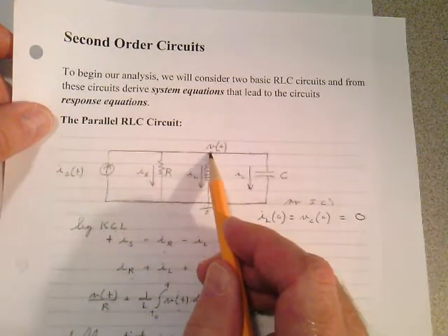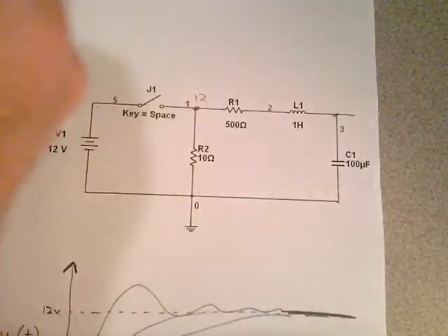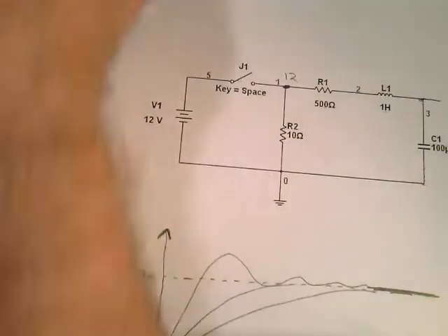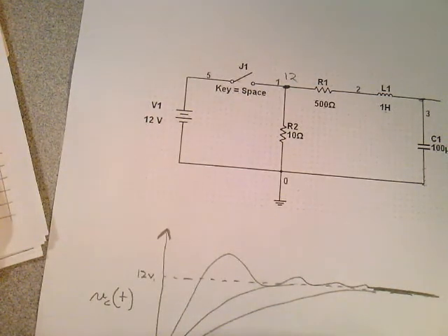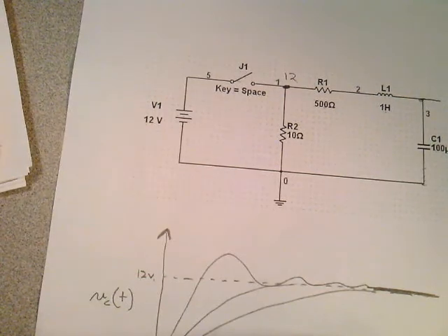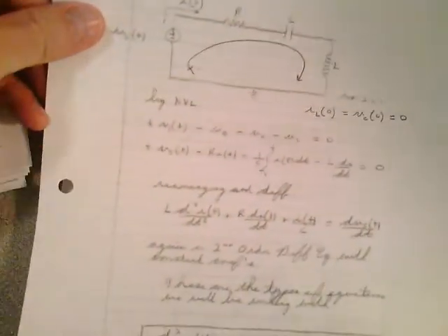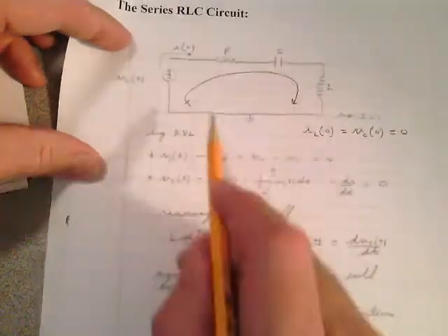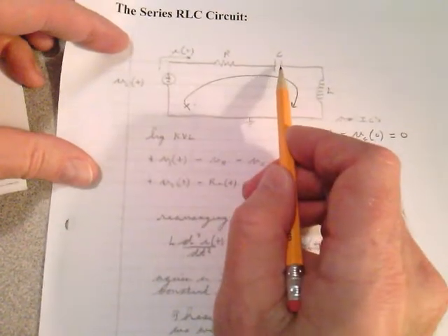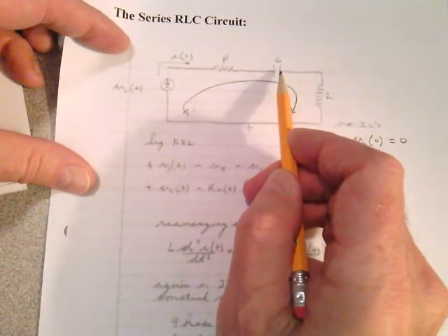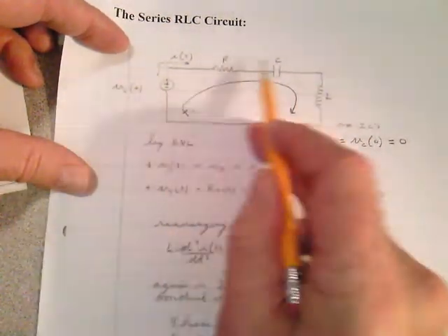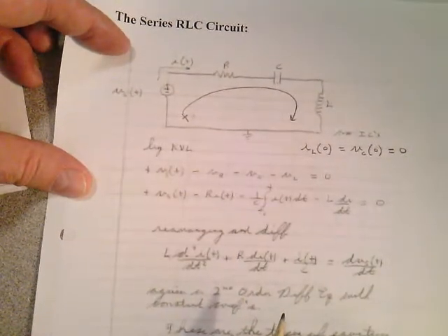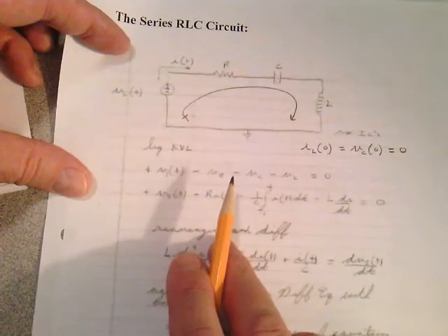And if you look at the second circuit and you're solving for the current, it's going to go to 0 because the capacitor is going to look like an open circuit at time t equal infinity, after the transient dies out, so there can't be any current.